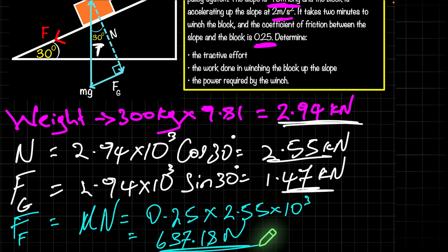So what we are doing effectively is taking something that's moving and treating it as if it is static. And when we do that, we are then able to balance our force components, and as such, we can work out these unknowns that we're after.